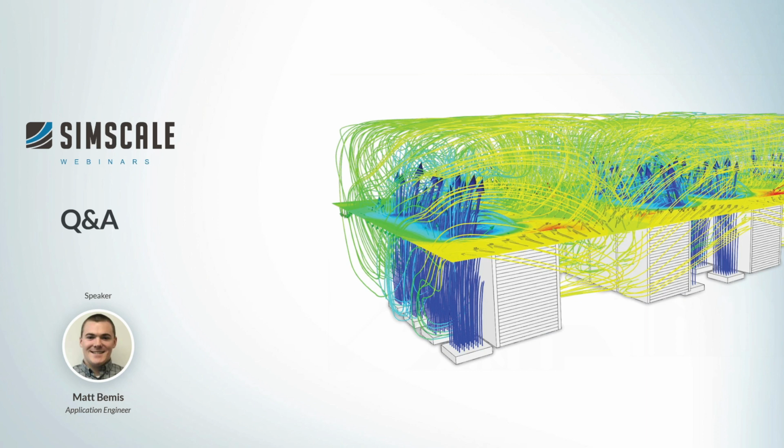Now, another question. The model I showed you today, we basically went to the rack level. We said uniform distribution, 8.4 kilowatts. The question is, can we actually go down to more detail? And the answer is yes as well. I've actually had customers, I think I mentioned this originally was a 42U rack and server cabinet. People have actually modeled all 42Us, or sometimes they're the 2U slots, so they do half of that. You can do that.